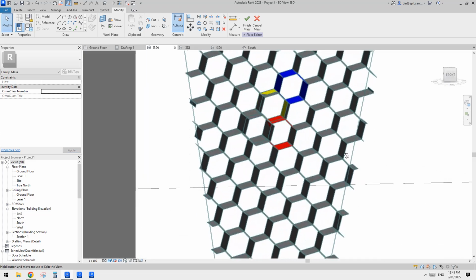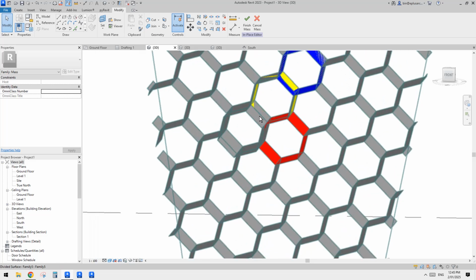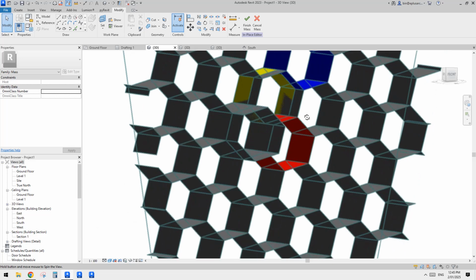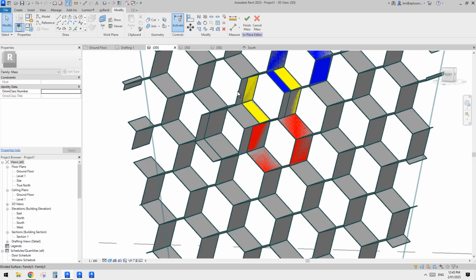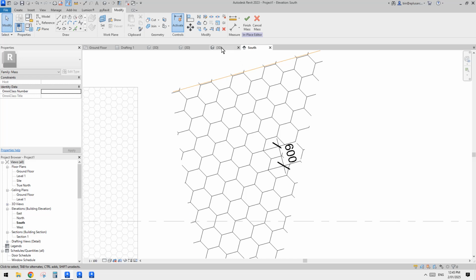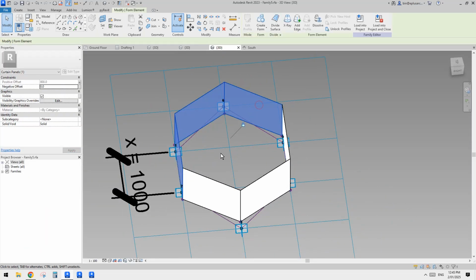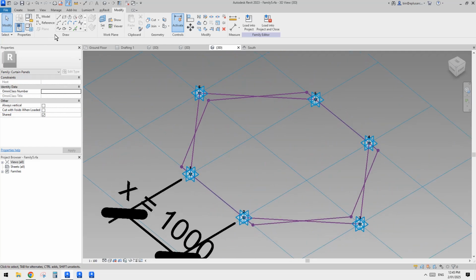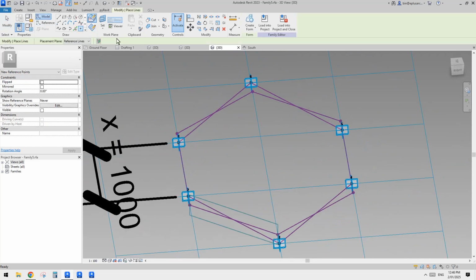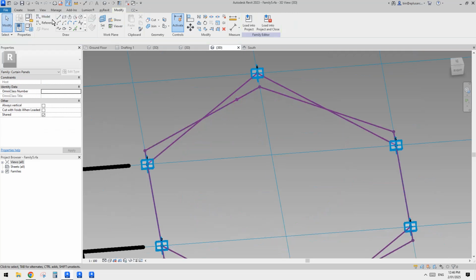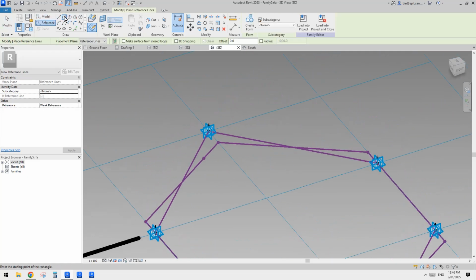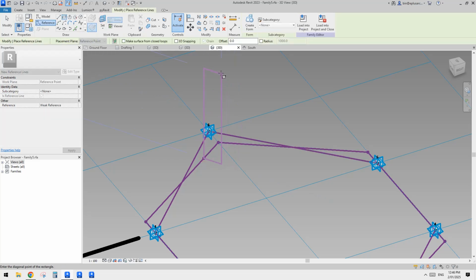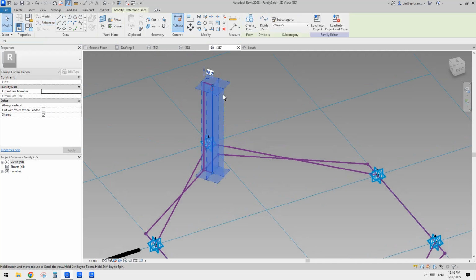I think that can be some issue. Or instead of directly extrusion, creating extrusion from these lines, we can do a sweep instead. So for example, I'll quickly place a line, use draw on face, and onto this create a profile, right? So reference rectangle, draw on work plane, set work plane, pick this work plane. I'll just draw it something like this, okay? And then with the thickness.